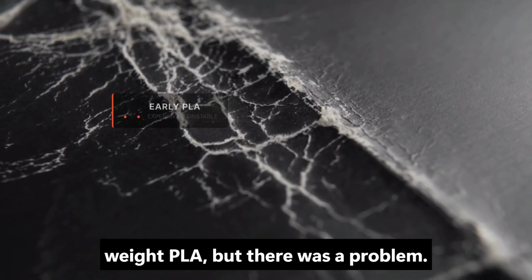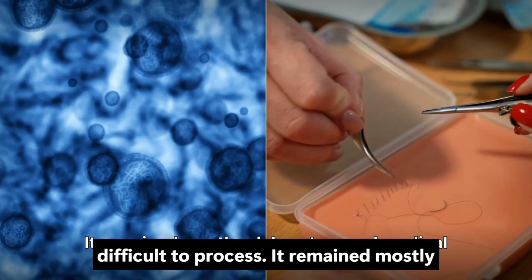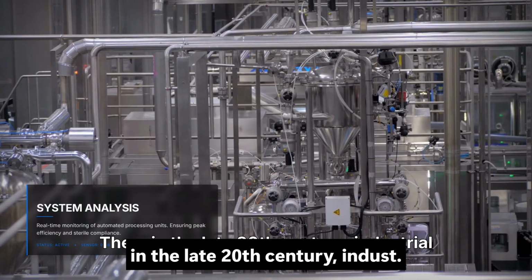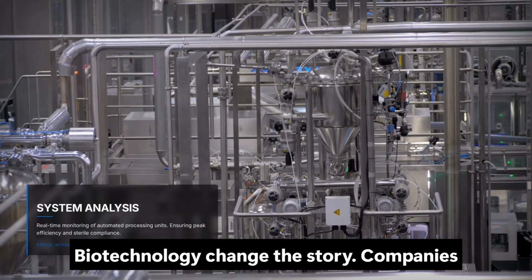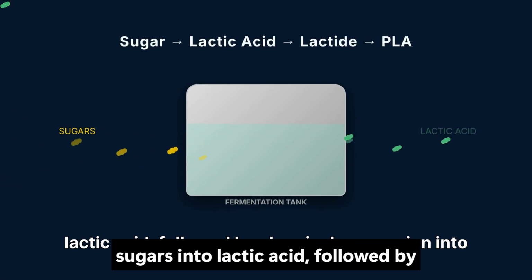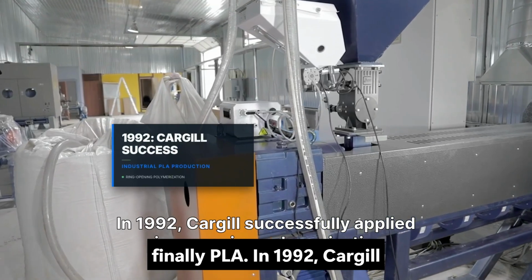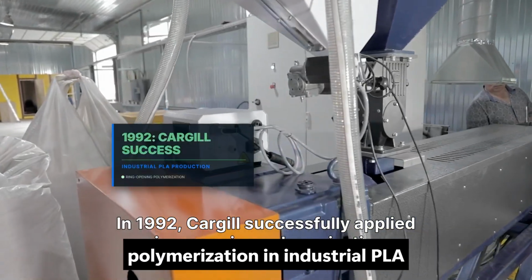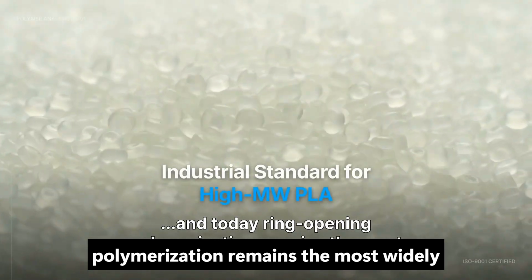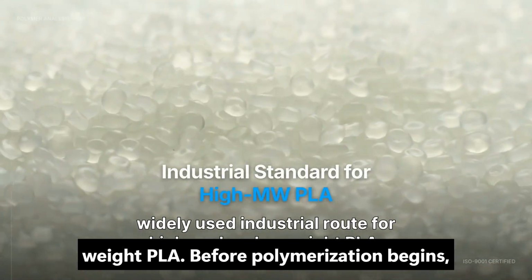But there was a problem. Early PLA was expensive, unstable, and difficult to process. It remained mostly a laboratory and medical material. Then, in the late 20th century, industrial biotechnology changed the story. Companies developed large-scale fermentation of sugars into lactic acid, followed by chemical conversion into lactide and finally PLA. In 1992, Cargill successfully applied ring-opening polymerization in industrial PLA production. And today, ring-opening polymerization remains the most widely used industrial route for high molecular weight PLA.